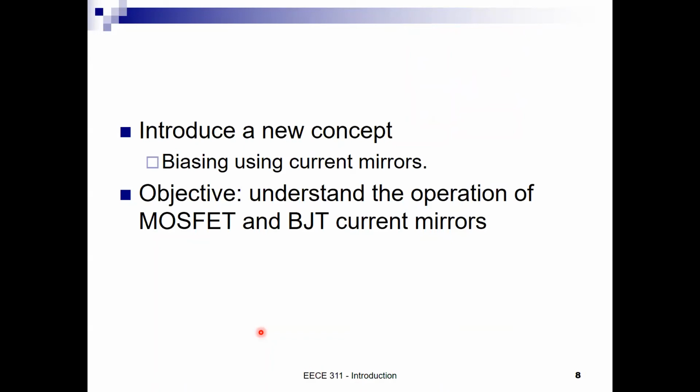Another way to do this biasing, and we'll take many of these examples, so don't worry about them, is to force on the circuit. If this is my transistor, I want to force on it a current source, okay, with a specific current value I, like the example before, which is 0.1 milliamps, okay. And let us say that I plug in a capacitor here in parallel with this current. So in DC analysis, what happens to this capacitor?